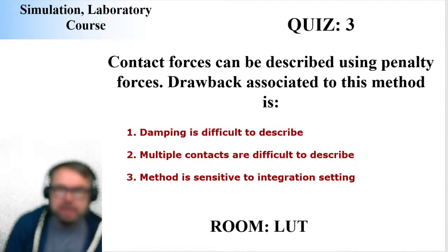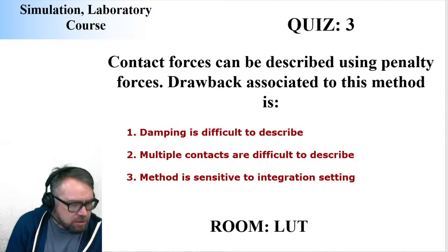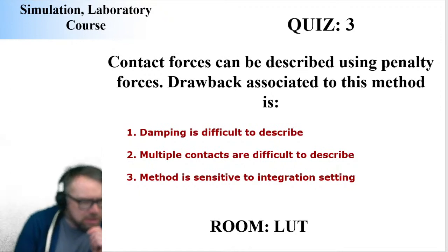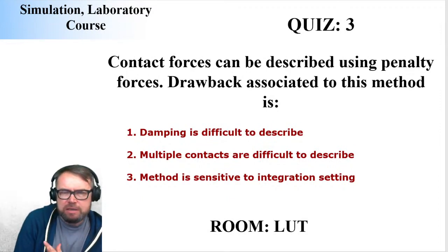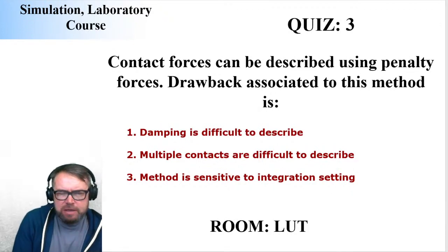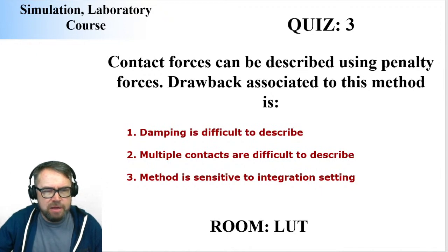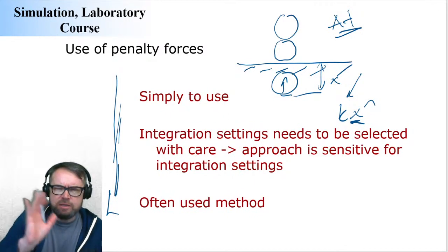Can the time step be changed when the object is getting closer to contact? Yes, there are time integration algorithms that are based on variable time step. So it's possible that when you see that something goes wrong or something happens, then you can change your time integration steps. But typically the problem is that, if I go back here to this one, you're using very high time step, even though you have this opportunity of changing your time step.